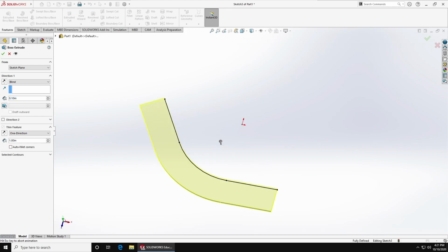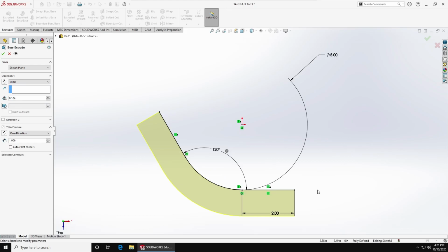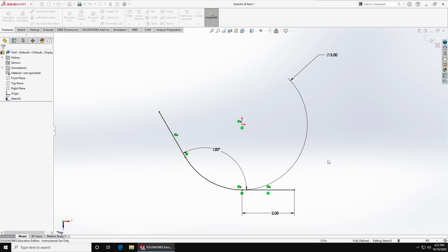It doesn't have any information of how you would like the surface to end, so it plops in a surface that's normal to the edge at that endpoint. Another way to think about it is that it makes a right angle with the edge once it reaches the end. Now, as I mentioned earlier, this is a sub-feature for revolves as well, so let's see how that works.